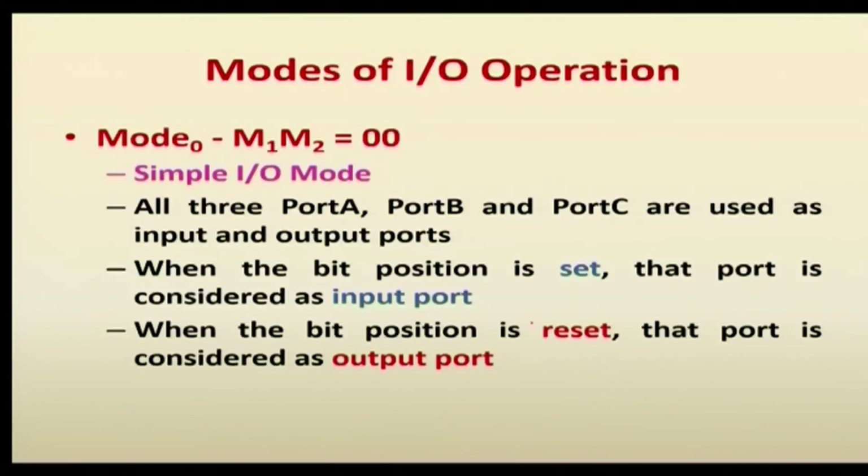When the corresponding bit is set, it means the corresponding port is used as an input. When the bit is reset, the corresponding port is used as an output port.